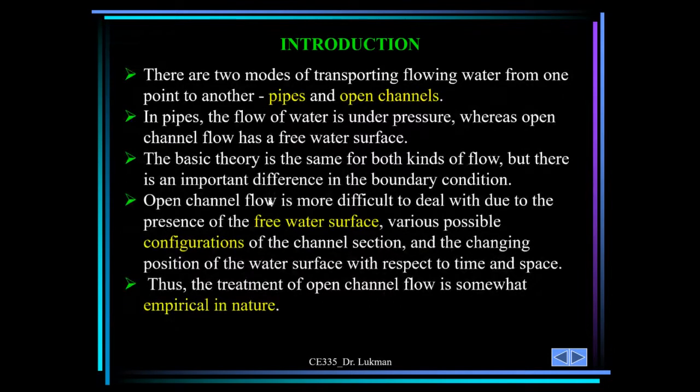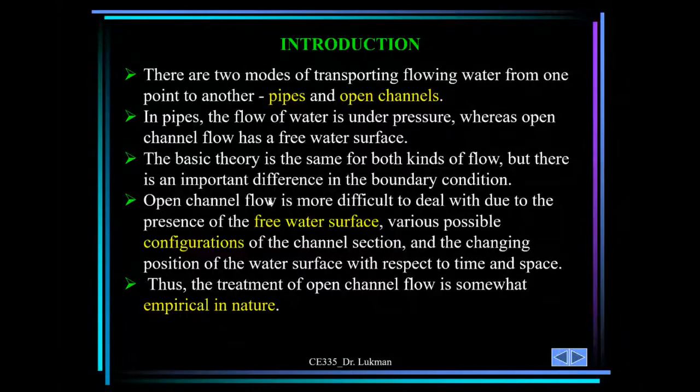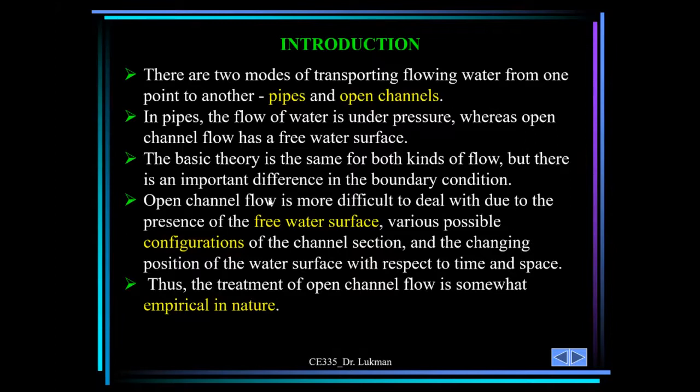And there are 2 modes of transporting water from one point to another: pipes and open channels. In pipes, the flow of water is under pressure, whereas open channel flow has a free water surface. Even for pipe flow, it can be under gravity, in which gravity will enable the flow of water in the pipes to be under pressure. But open channel flow has a free water surface which is acted upon by the atmospheric pressure.